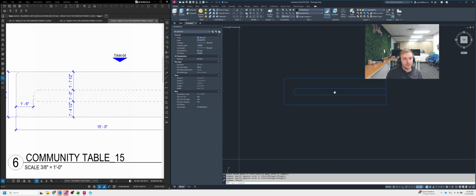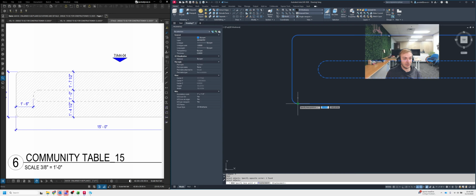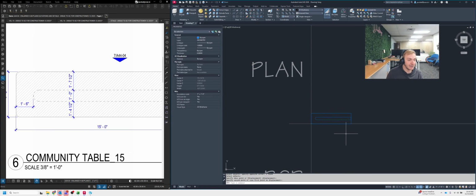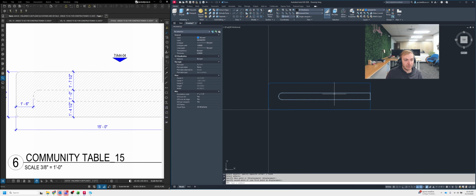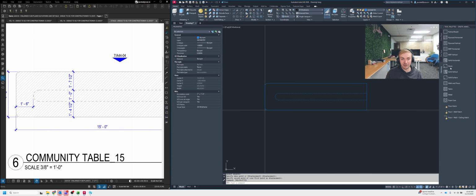All right. Now, if I really wanted to, I can make this a hidden line because really that's what that needs to be. And then we're going to take this and move it right to here. I'm going to take my corner using the move command, and I'm going to place this geometry right at the corner of my grid like this to be in square with everything that I've got. Now that we've got the plan view drawn, maybe I can even add the die walls in, so I need to open my tool palettes here, go over to my annotation tab, and we're going to pull in the floor hatch, which we're going to use as a wall.